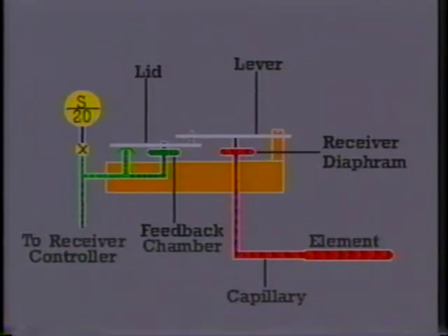The only flow that takes place is between the restrictor and the control port. So it is important to locate the restrictor as close as possible to the transmitter. This minimizes the distance through which the flow travels and subsequently minimizes the pressure losses.